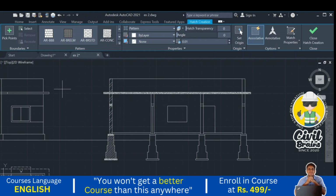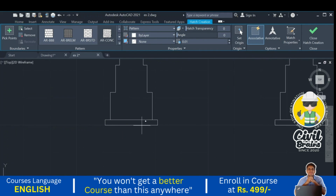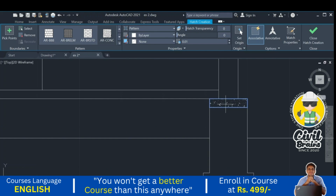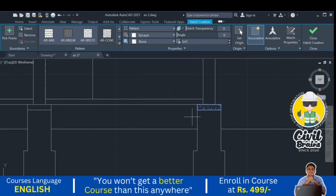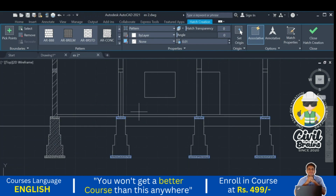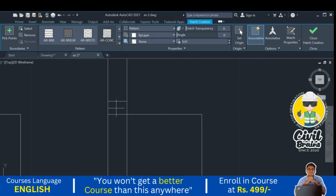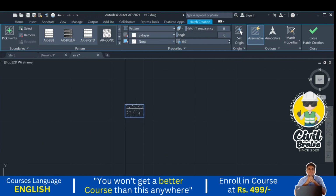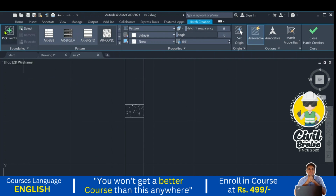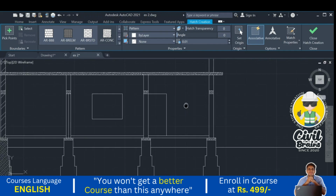I'll just quickly hatch that one. So which is concrete, or here concrete, and here concrete, and here concrete. Just click on here concrete, here concrete, okay, here I just put here, escape. Again go to the hatch, add pick point. You can do the pick point or directly point will take.